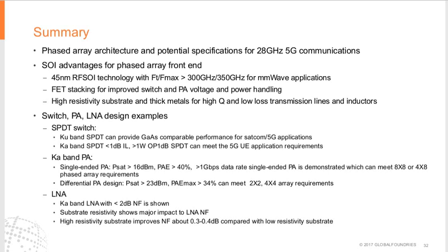So the high resistivity substrate and the single metal are very important from the LNA point of view. It's very important for the noise figure. From the PA point of view, the output balun is very important for the PA to maintain high PAE and also reasonable P saturation power.